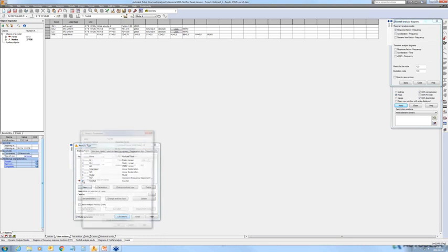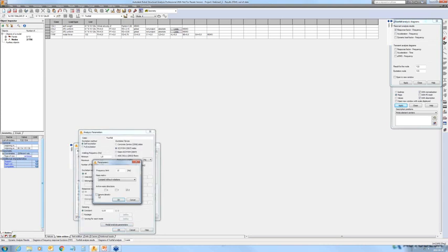And also, if we have footfall, we should do the same in the parameters of modal analysis for footfall. And also mind that in the footfall, only Z direction for mass is active.